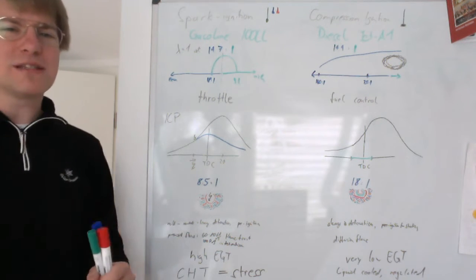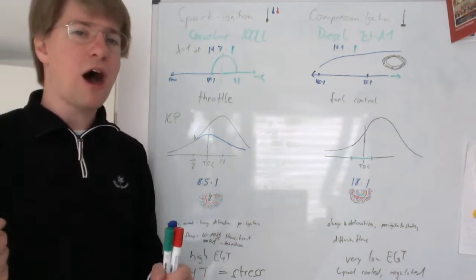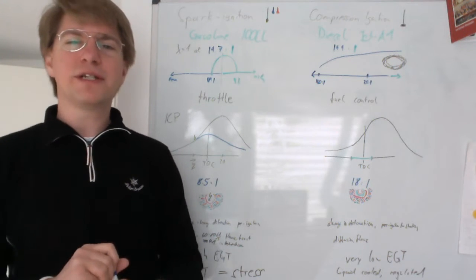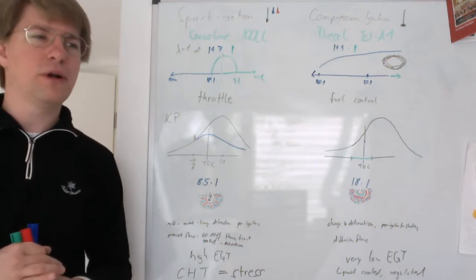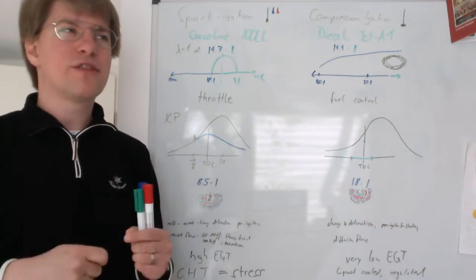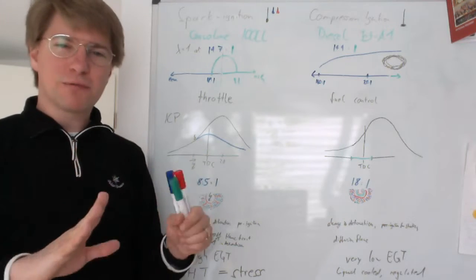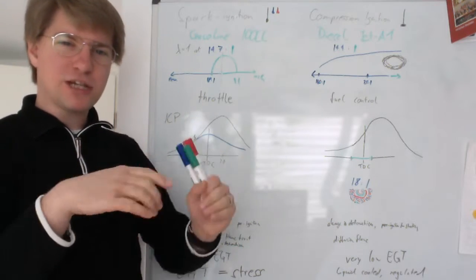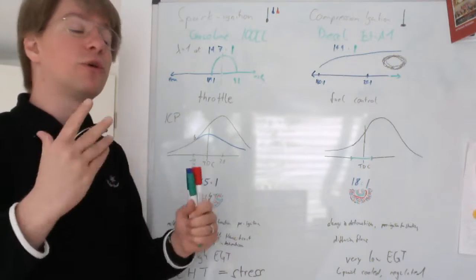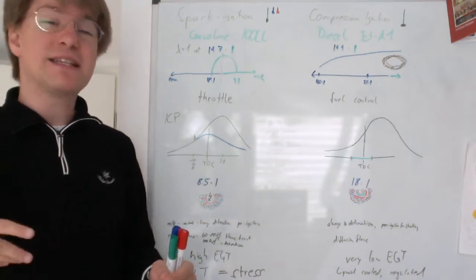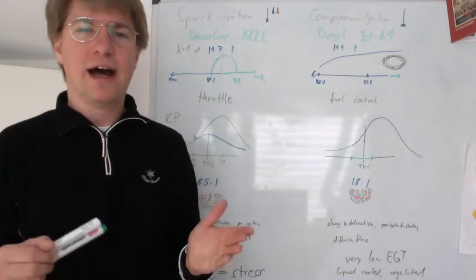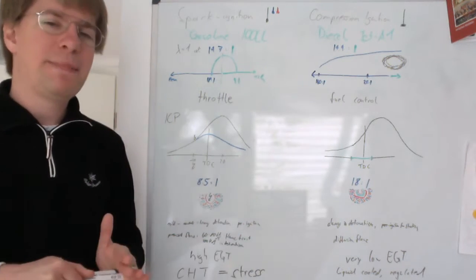The only reason why they did away with the blue knob is that these engines are FADEC, Full Authority Digital Engine Control, and the FADEC system also controls the propeller. But the principle of the propeller, that it is variable in pitch and that it has a governor that changes the pitch of the propeller blades in order to keep the RPM, that is exactly the same as with a gasoline burning, 100 low lead burning piston engine.